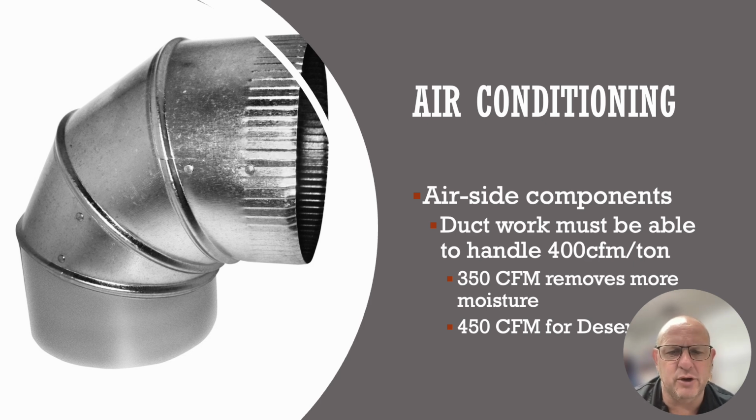Now, that airflow is going to be distributed throughout the entire structure. So if we ended up with a 2-ton system, we'd end up with 800 CFM of air flowing out of that. We'd put 150 CFM into a couple of different rooms, depending on the heat load calculations that those particular rooms needed, until we have exhausted in totality the 800 CFM of air needed for that system to operate properly.